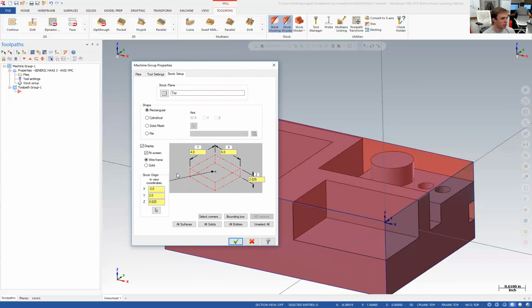And then it's also helpful for a couple other settings in toolpaths, such as, it's actually called stock, but it looks back to the stock to see what needs cutting still. I won't go into that any further now, but it's really important that you know how to do this, and most of the time you need to. There are a couple instances where you won't actually need to set up a stock definition to accomplish your toolpath. Okay, so we've talked about how to do it manually with these 6 yellow boxes.